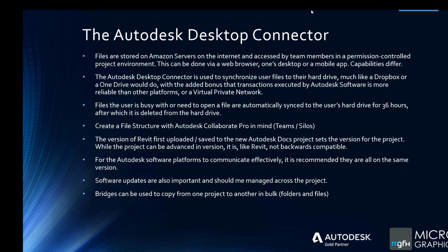That's very important to remember. So use the version of Revit that you would like the platform to be on. It's not backwards compatible. Not even Autodesk can reverse that for you. You will have to create a brand new project and start everything from afresh. And if you've got, say, 100 users and you've assigned permissions and you've invited everybody to the project, then you'll be bothering everybody else with the second invite and permissions and everything else that you have to set up, which is no fun. Yes, you can use a sort of template if you want, but still, it is not a pleasure to have to set something up twice when you can do it better the first time.